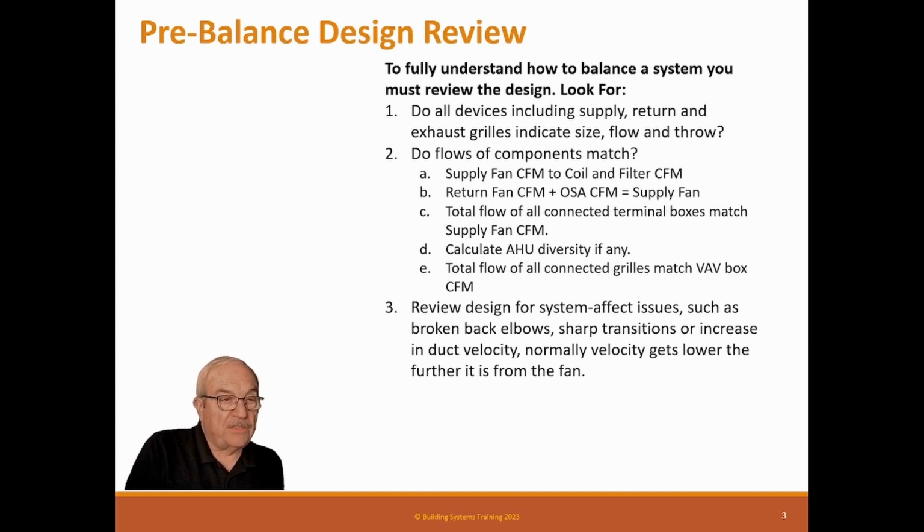So if you have a duct system that starts out at 2,400 feet per minute, goes to 1,800 feet per minute, goes to 1,000 feet per minute, and all of a sudden goes back to 2,400 feet per minute, that's a problem because it takes horsepower to go up. It's free going down. When velocity goes down in a duct, the duct sides cause friction and slow the air down and actually convert the velocity pressure to static pressure, and that you get for free. But when you need to go back from a low velocity to high velocity, that costs horsepower. And that's a problem.